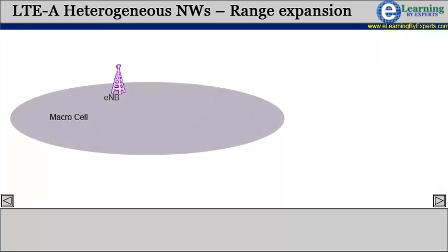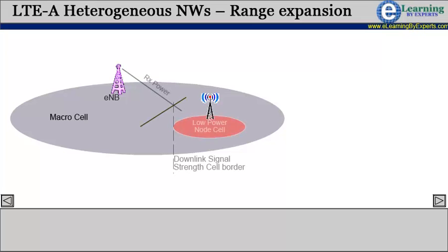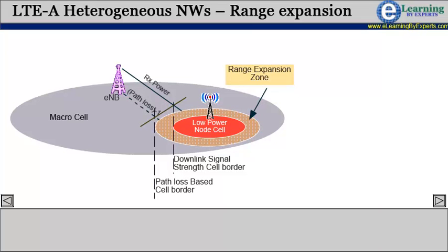Typically, there are two borders to the picocell, PC/femtocell, FC: the conventional cell edge where the downlink signal from the PC is the strongest one, and a so-called cell range extension, CRE, where the path loss on the uplink to the PC is still smaller than the path loss to the macrocell, MC, whereas the downlink signal from the MC is the stronger one. The reason behind this asymmetry is the difference between the transmission powers, which is usually much higher for the MC compared to PC/FC.